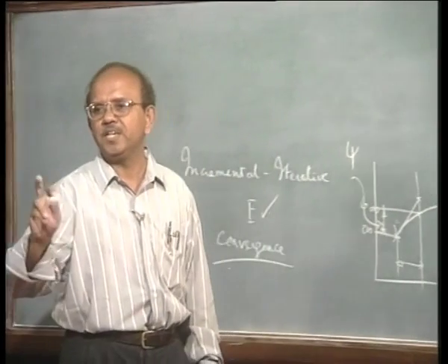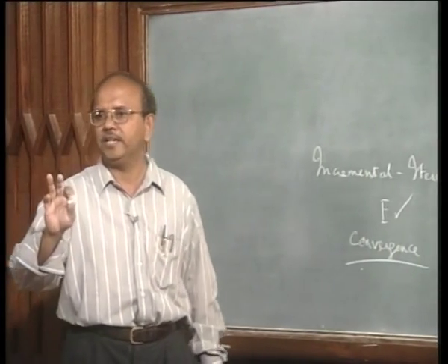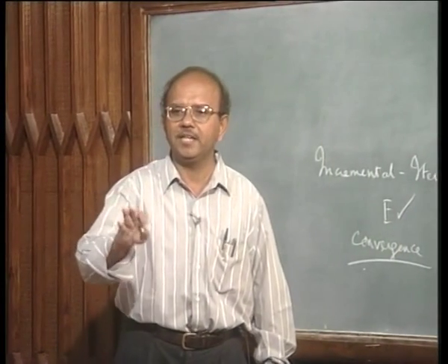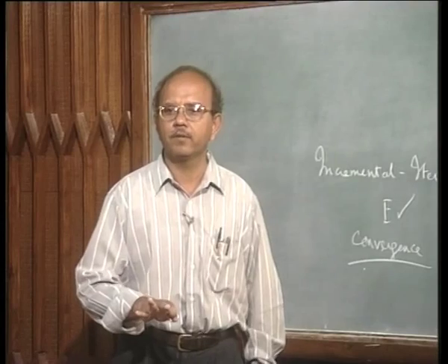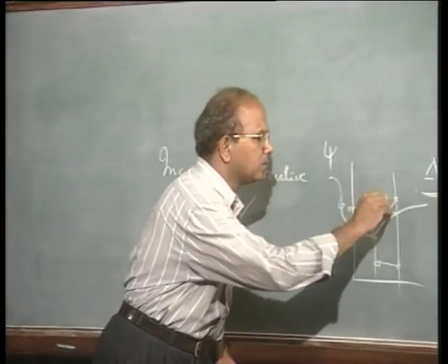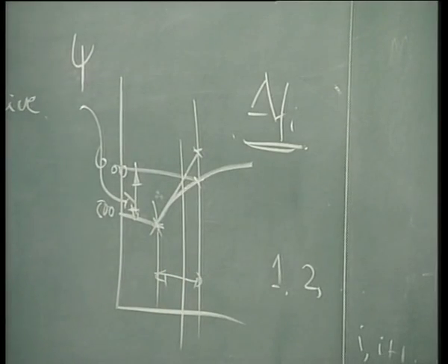B transpose dB, where instead of E in D I put Et. So I calculate. In a one dimensional problem, what will this lead me to? See, AE by L, remember that. So I will just substitute Et instead of E.